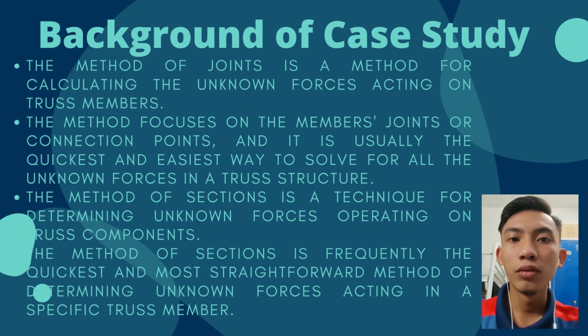Labeling the members of your truss is usually helpful at first. This will make it easier to keep everything organized and consistent in the future. Draw a free body diagram, write out the equilibrium equations, and solve for the external reaction forces operating on the structure system. Treating the entire truss structure as a rigid body, this analysis should be comparable to that of a single rigid body. After that, envision dividing your truss into two halves.